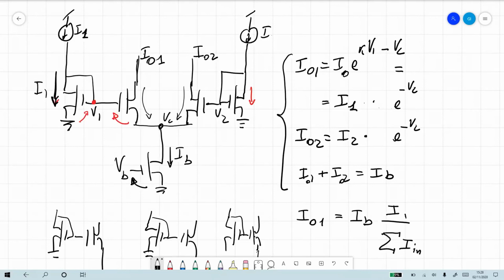So in this sense, this is a winner-take-all circuit, and it can be adaptively adjusted so that when you pay attention to something, you enhance those inputs and you suppress the others. First, you need to normalize everything, which is what we can do with the Gilbert normalizer. But then you also need selective gain, selective amplification.